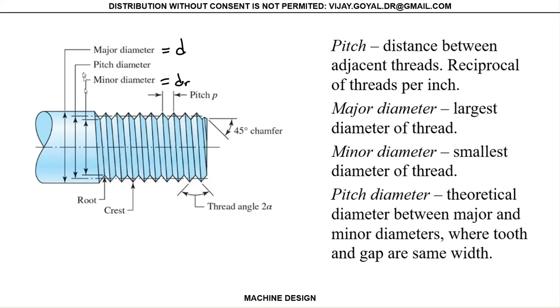Then the pitch diameter is mainly the mean diameter between these two diameters. And sometimes we also call this d_p because it's pitch or mean. Many textbooks and places you go to interchange this back and forth, but it really means the same. And the outer diameter is, if we just take the full length right here, that's what it will give you.